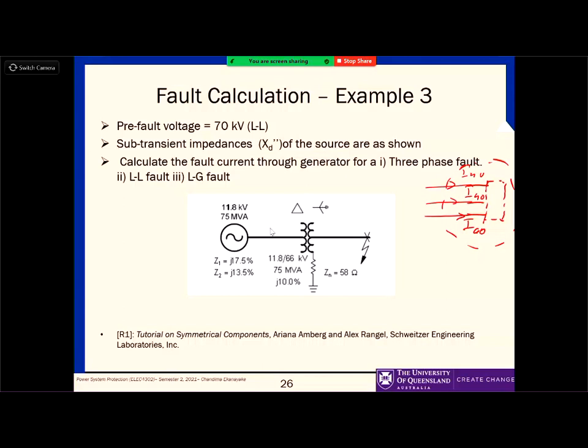So that's why when you have these sort of delta connected systems, you have 3 wires, but there is no return wire there. If the current comes in and there's no way to take it back, which means that in this part, there is no zero sequence.